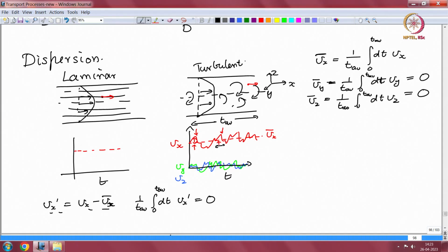The fluid velocity field consists of two distinct kinds of velocity fields. One is laminar and the other is what is called a turbulent flow. In a laminar flow, there are nice straight smooth streamlines. The velocity field at steady state is independent of time, and at a location, if you measure the velocity, it will be a constant. As the Reynolds number increases, there is a transition to a turbulent flow, which consists of large fluctuations in the velocity.